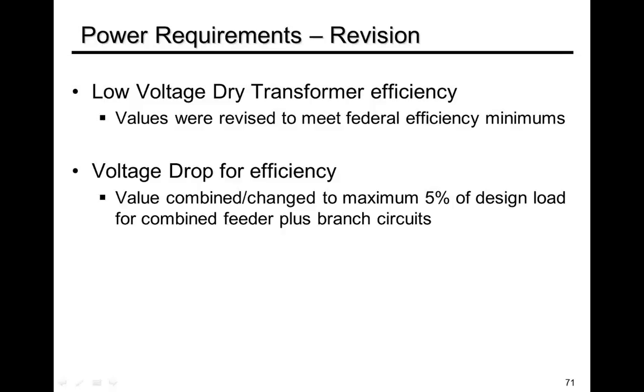Previously, this was done separately for feeder circuits and branch circuits, and there was a lot of concern about that over many years. So it's been combined into one requirement, just a 5% design load for a combined set of feeder and branch circuits. Makes things a little simpler.